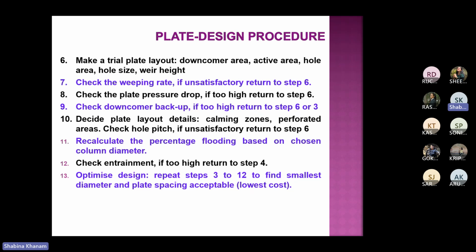Okay, so if you recall, we have discussed three different trays: a sieve plate, bubble cap tray, and valve tray. Bubble cap has the widest range of flow rates it can handle, in comparison to valve tray and then sieve tray. And valve tray is better than sieve plate if we are considering a lesser flow rate.